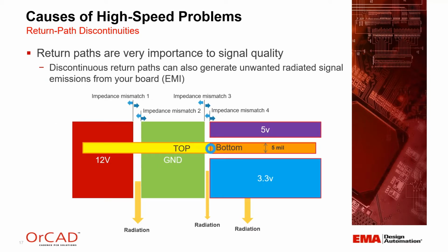Some of the problems they cause, like I said, they affect the impedance of the signal trace. So anywhere along the signal conduction, if there's an impedance mismatch, and there's not a reference close, in other words, it's crossing a void or something, usually that involves a radiation effect, because the energy is trying to resolve itself back to a potential back to the source. And if that's not in a convenient distant space, it basically results in a radiating result of the electric field and the magnetic field. So this is usually where EMI problems come from, where you have impedance mismatches due to void crossing.